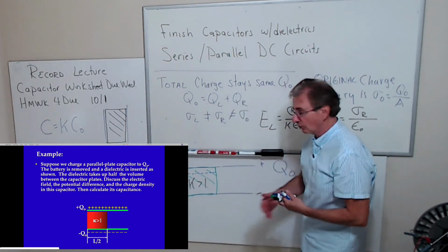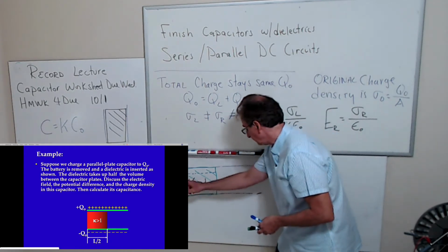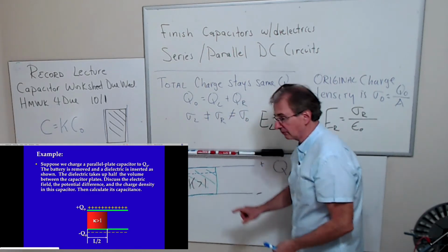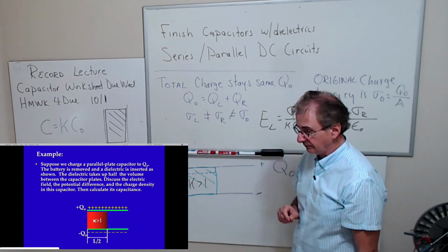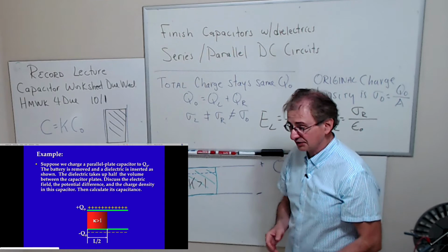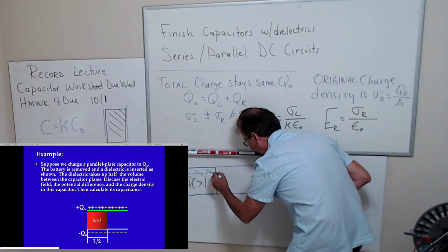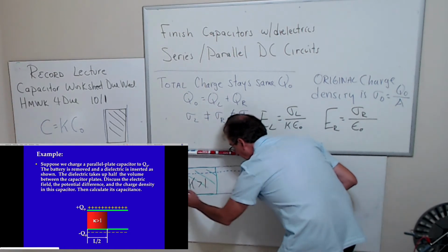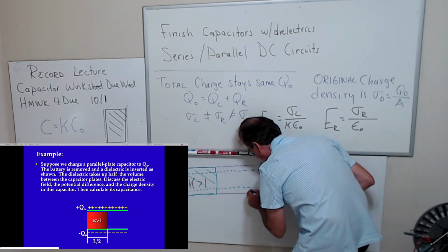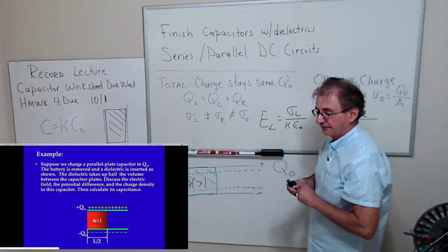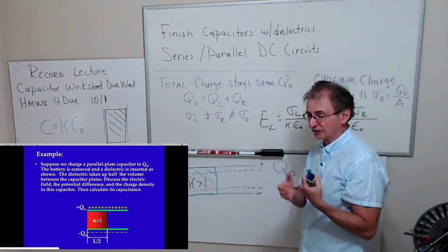So what happens when you reach the boundary? You march across here, the potential is 1 volt, you hit the boundary. What must be true when you reach the boundary? The potential has to be continuous. So if the equal potential is 1 volt all the way across here, it must be all the way the same value all the way across here. If the potential is 5 volts here, along that dotted line, then it must be 5 volts all along this dotted line. It can't change at the boundary because otherwise you have an infinite electric field. It's not physical.